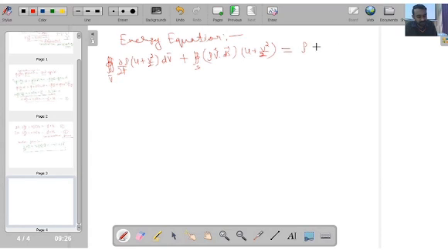first term because of the heat generation. Here ds I have already written. Say if q dot is the volumetric heat generation, the rate of heat generation per unit mass, then it will be rho q dot dV. This is the heat generation term.